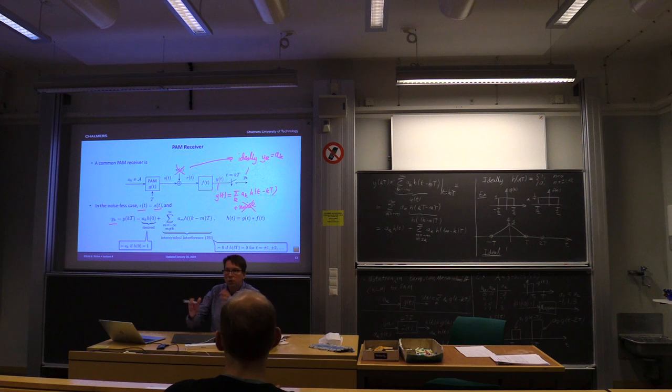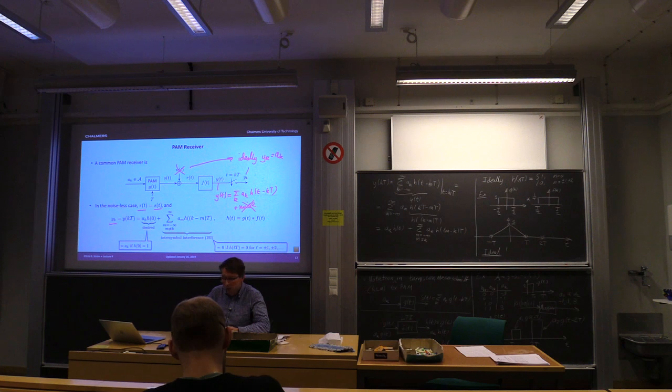It has to be confined in frequency. And the reason for this is that the transmission medium might not be conducive to all frequencies. It might have band limitations. Or if this is a wireless signal, it's very important to keep it confined to its channel, right? Otherwise, it will create too much interference with other things.